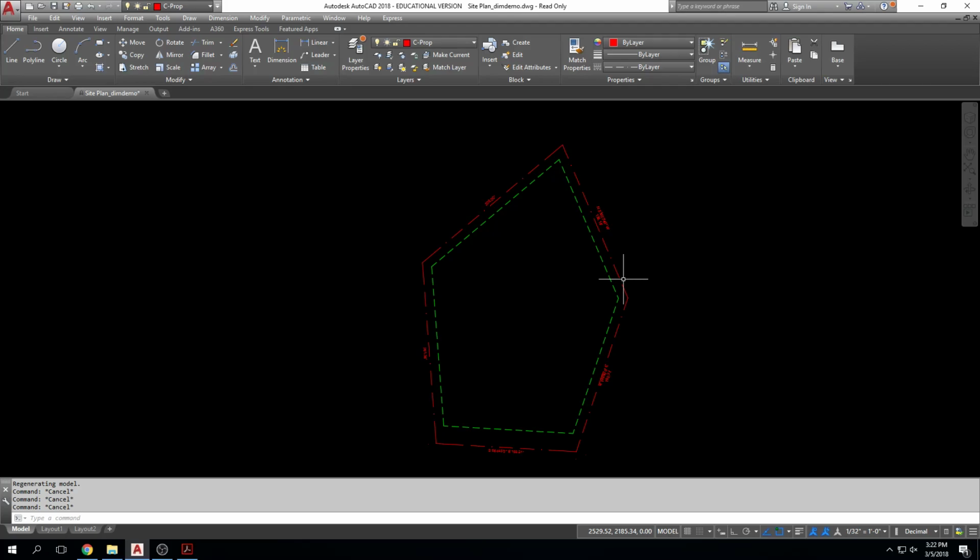Yes, that's fine. How would I scale back my dimension line after that? Enter, hit enter. Now click on the line, click again. Maybe your site plan was the right size in the first place and I told you wrong. Maybe it's a combination of weird things that happened. What was the problem before? It was displaying 2,460 inches instead of 205. It was saying 205 there though, right? Yeah, on this one it says 205.